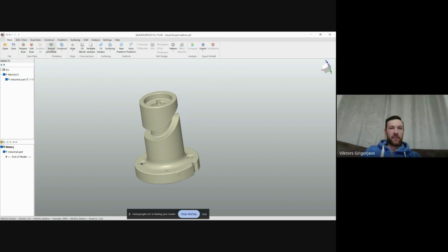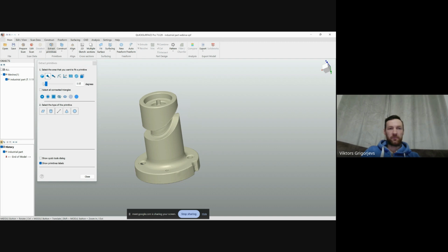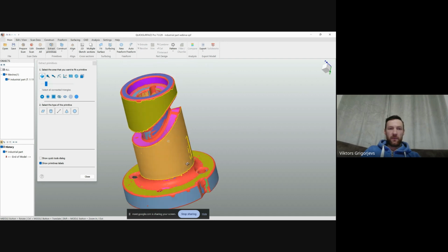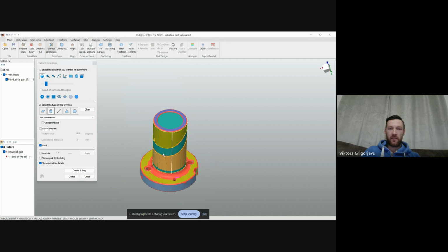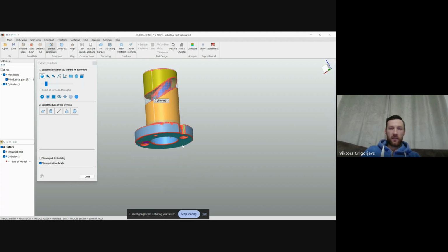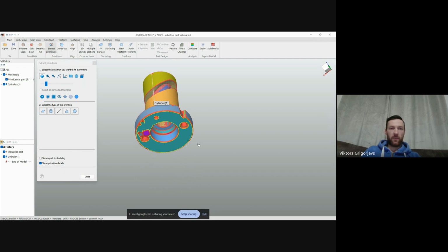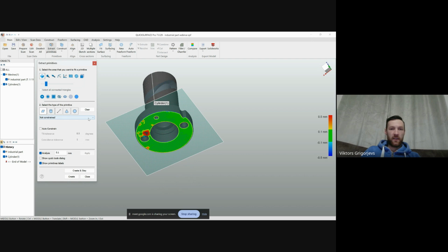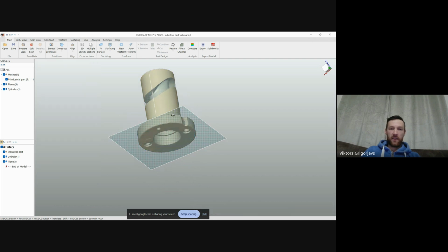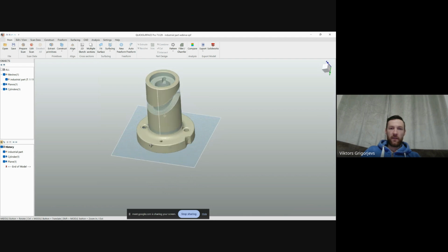Okay, as always, we're starting with extracting primitives so we can align our object to the coordinate system. This time I'm going to fit a cylinder to this surface. It's another primitive. I'm going to fit a plane here that will be constrained perpendicular to the cylinder. That's the third reference.